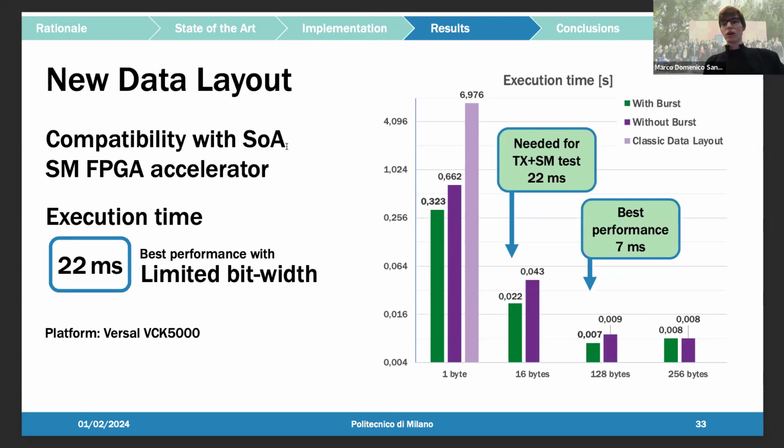Exactly. While scaling the bit width, the reading speed increases so much that the application might end up no longer memory bound, but compute bound. Moreover, there are limitations related to the bus and to the memory banks. So further study may help determine if it is feasible and even useful to parallelize the computation so that the design becomes no longer compute bound.